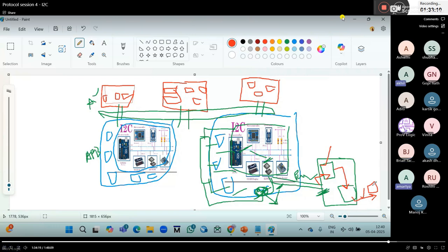Yeah, this is the same, right? All the Synopsys IPs will have these APB or AXI interfaces over them. Correct, that is the idea. Any IP we purchase from Synopsys, whether it is I2C or UART, everything will be covered at the boundary level of the IP. It will be an AXI or APB or AHB interface, which will interact with the main interconnect AXI. Correct.